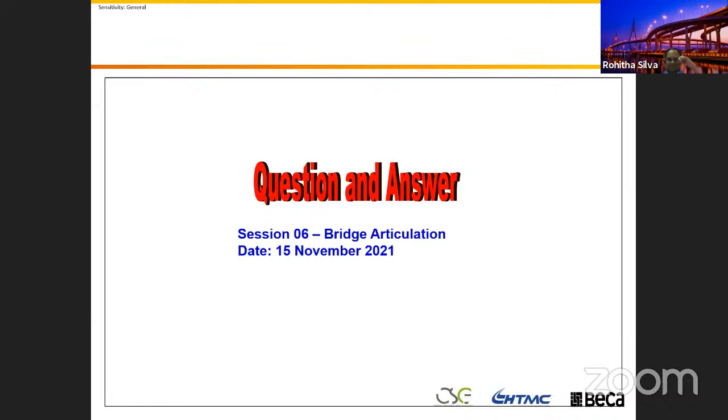Even, for example, the Australian standard is quite good. They explained it in one volume. It's AS5100 Part 2, which we call the loads. But if you are using the Eurocode, or the British standard, so no British standard now, of course, now it's Eurocode. If you're going to use the Eurocode, you have to use a couple of different volumes to extract the forces. But still, I think you can combine them together